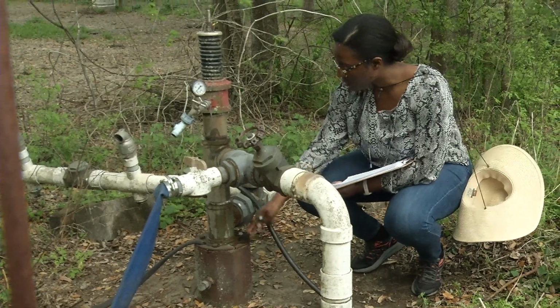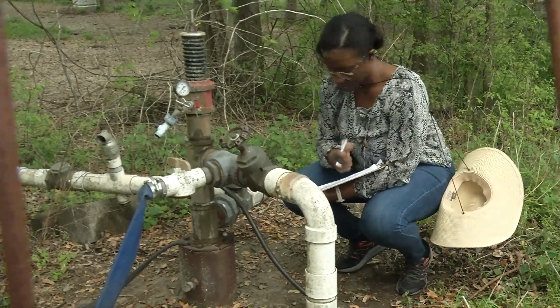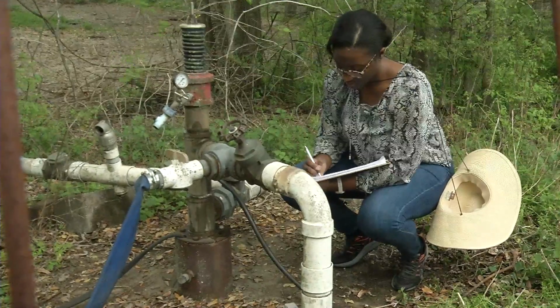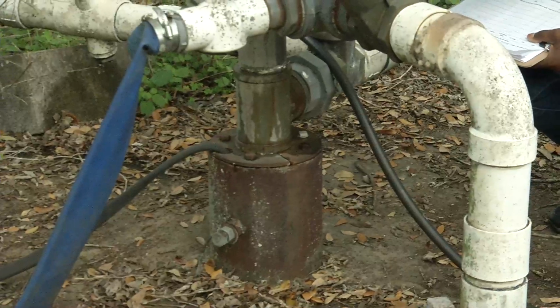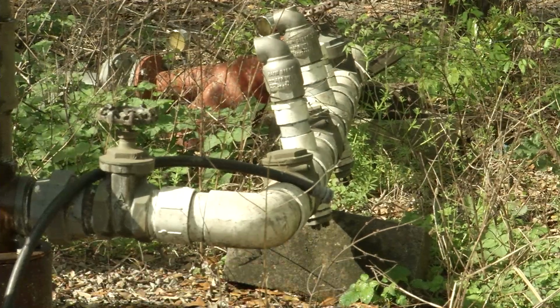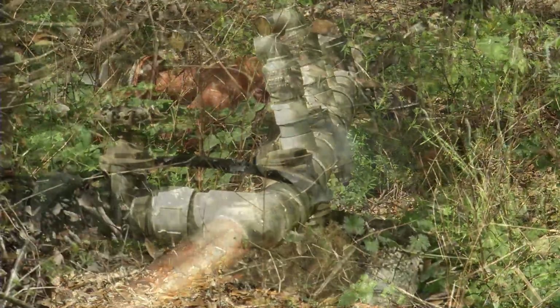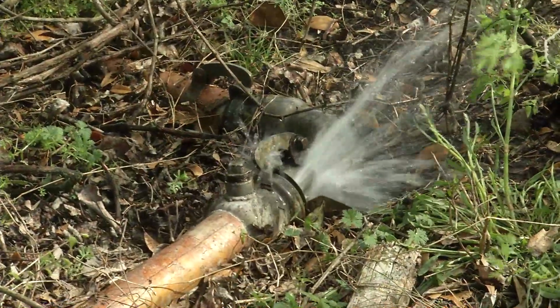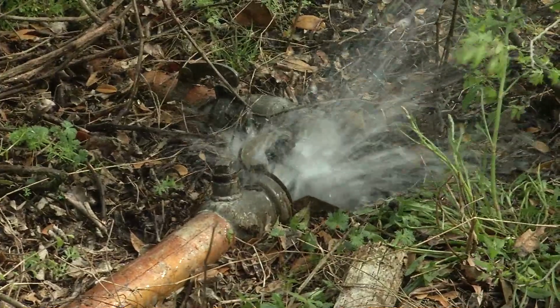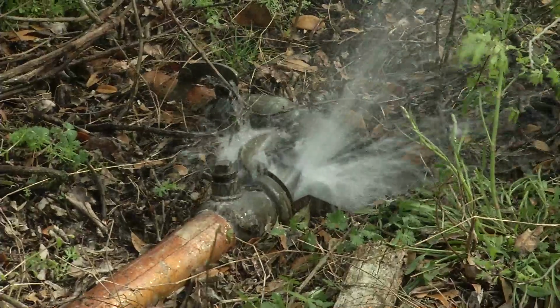To prevent pathogens from entering your water distribution system, you must inspect the distribution system. This includes wellheads, emitters, irrigation lines, and hoses. Equipment that's not constructed properly or that's damaged can increase the risk of pathogens entering your system.